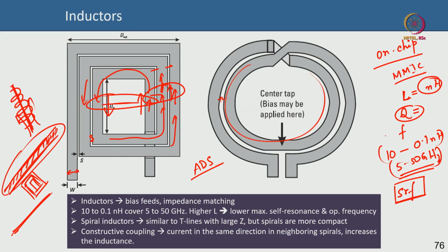What is the underpass? This is the underpass, you see. You cannot have a metallic short between the two lines that are crisscrossing over each other here. So you need to design the fabrication such that one end of this line is going below the other end and they are separated by a dielectric, such as silicon nitride, for instance. Okay. So there is a dielectric that is separating the two. The fabrication process flow has to be designed such that you enable that. Okay. It has to be thoroughly qualified, optimized.